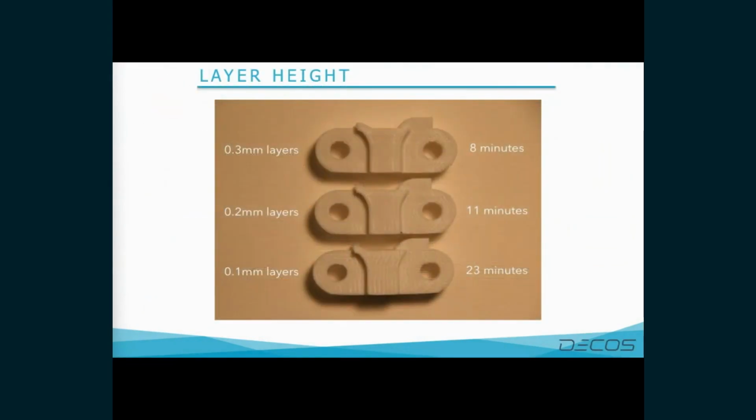As previously mentioned, layer height affects the speed and overall print time of your object. Layer height affects print time because your print head has to print each layer one by one. A smaller layer height means your object has more layers in total. The impact of layer height is more noticeable on curves and angles, and it is less prominent on straight vertical walls due to the layer by layer nature of 3D printing.